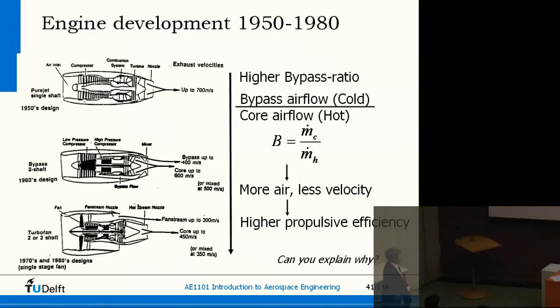Why is that? It's also nice for noise, and we often see in aviation that airlines or manufacturers want to show how green they are, so we want to create less emissions and we want to make less noise, and look how green we are. But very often, if you look underneath, there's another reason. If you create less emissions, you use less fuel, and that's of course something every airline wants. And similarly here, the noise is really nice, but in fact it was a side effect. The main reason was something else, the propulsive efficiency.